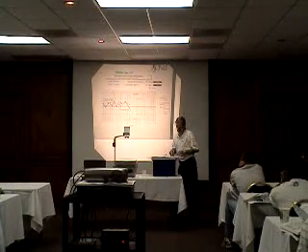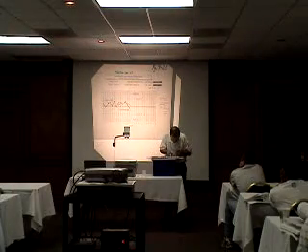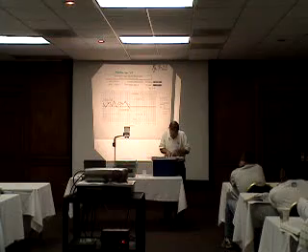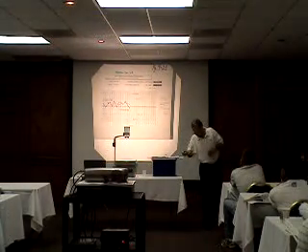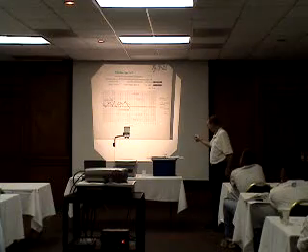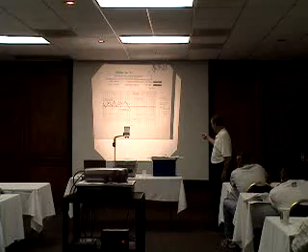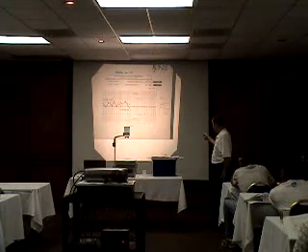If you look in the table, the moving average on the 075 is plus or minus 1.5, and the individual is plus or minus 2.5. So we come on our graph and we go up 1.5 from our target, and we draw the dashed green line. The dashed green line represents the moving average limit.